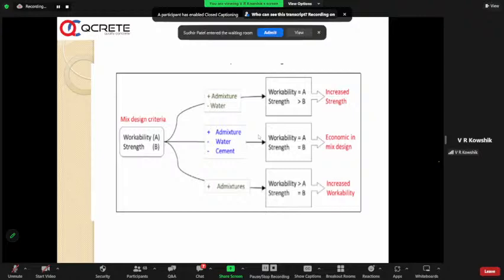Now, with the advancement in concrete technologies, we are making the same M25 at around 300 to 320 kg, almost 80 kg of cement reduction, and hence 80 to 100 kg of carbon dioxide emission is reduced. That is how the technology has moved from 1990 to 2023.